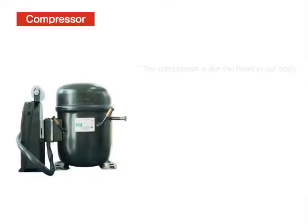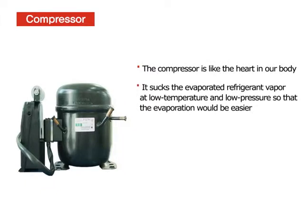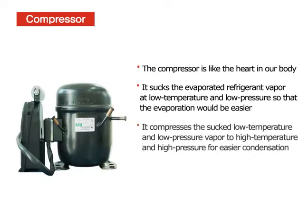Now I will explain about the compressor. The compressor is like the heart in our body. It sucks the evaporated refrigerant vapor at low temperature and low pressure so that the evaporation would be easier. It compresses the sucked low temperature and low pressure vapor to high temperature and high pressure for easier condensation. The compressor also circulates the refrigerant.